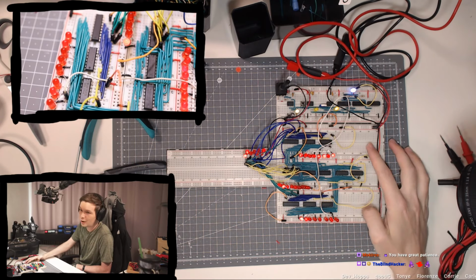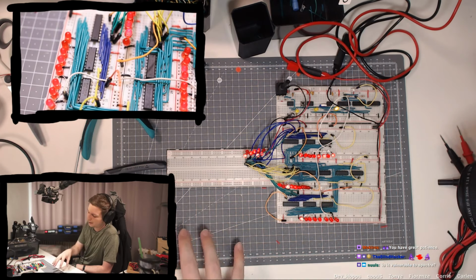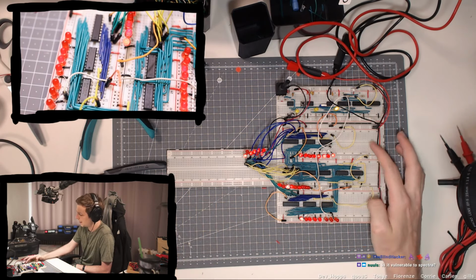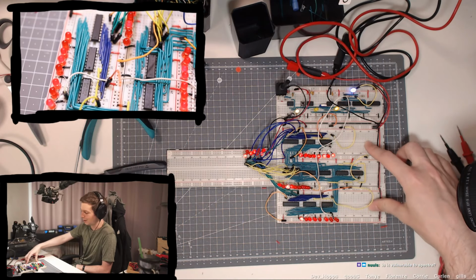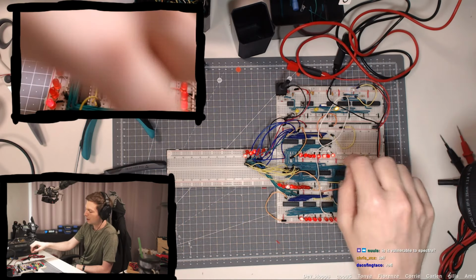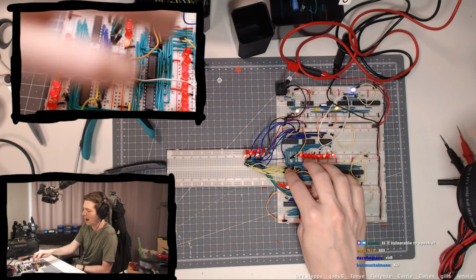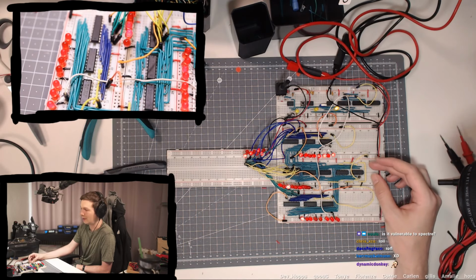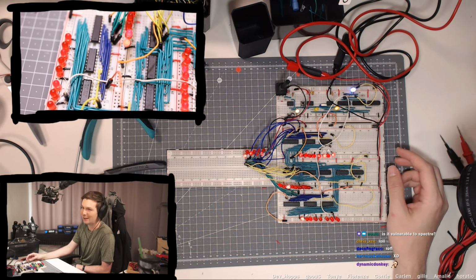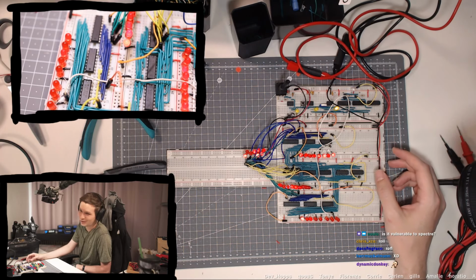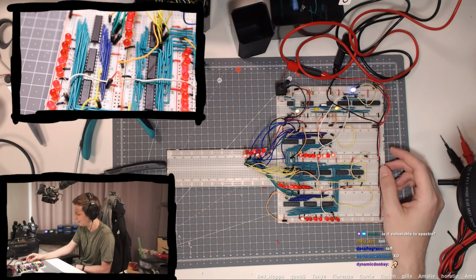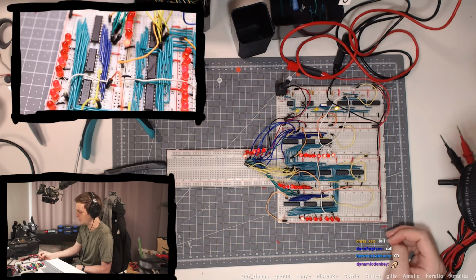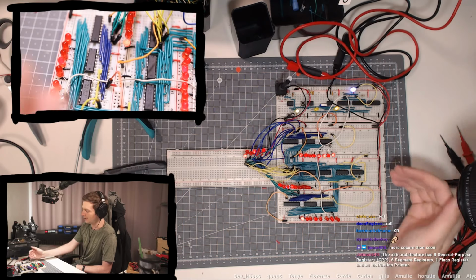So this CPU so far has 2 registers. There will be a third one, I believe, the instruction register that holds the address of the next instruction to execute. But yeah, this CPU is very limited, has only 2. These 2 registers are connected through an ALU, the arithmetic logic unit, and these are the chips here. So this module can do arithmetic. In our case, it can do addition and subtraction. So also not very fancy, no multiplication, no division, just adding and subtracting. And this is implemented on these chips there. And so far we have that.